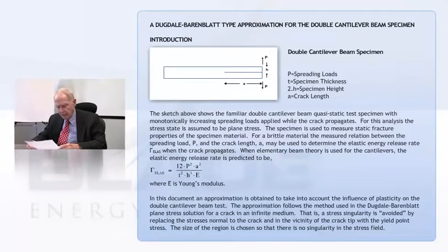Okay, and now you want to get the properties of what's going on. Now, the underlying equation for this is remarkably simple, and it's one of the things that shows what a bright guy Jim Rice is. He looks at this and he says, looky here, this is just 2 beams. I'm pulling them apart and they're attached back here at A. So I'm just going to use beam theory, and I'm going to calculate the work that gets done, and I'm going to calculate then, if the crack extends, what the energy change would be. So when I get to the point where the crack does extend, I'll know my load, I'll know A, and therefore I can use equation 1, I can get my gamma, and it's based on totally elastic theory. And that was the first thing that was out, and this was used as long as the elastic theory was thought to be good.